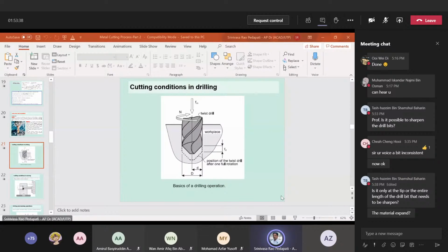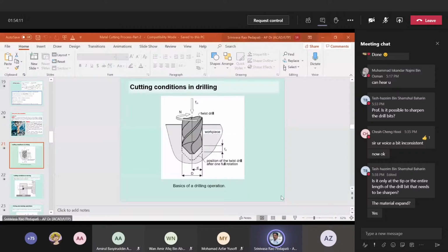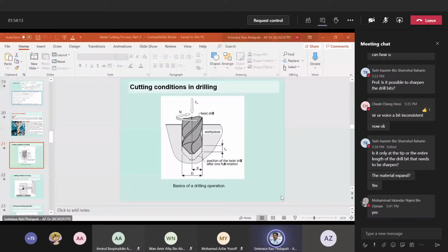Normally, as we learned in casting also, you want something, you make a pattern of more size. Why more size? You make the pattern slightly more size than the required object. Then your object is contracted and you get the right dimension. Is that what we discussed in casting? The pattern is slightly more than the cavity that you intended to get.